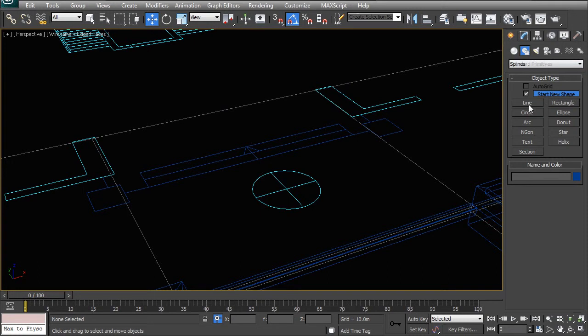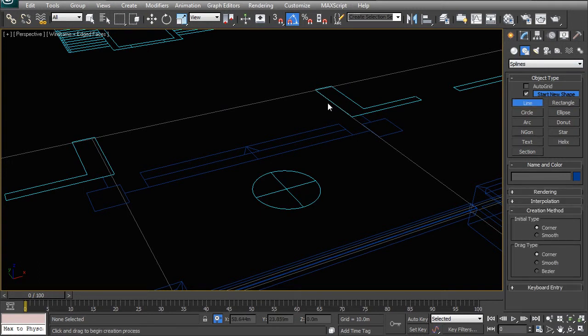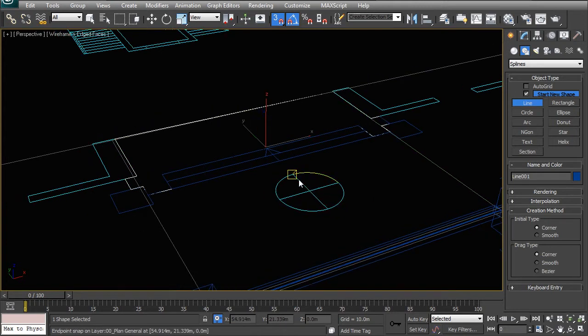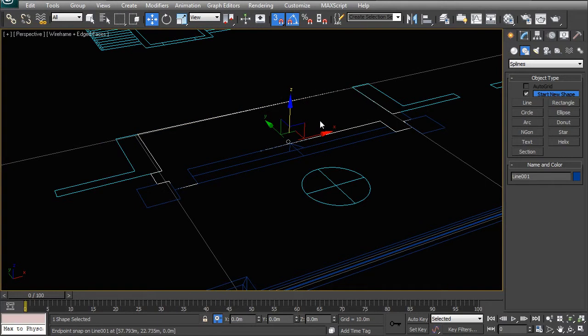So I'm going to start drawing that slab by doing a line, and selecting my snap, I just trace what the CAD information is giving me. And I'm going to select or at least trace the uppermost layer. I'm going to close that spline, and this will now be at zero. And all these steps will move down from it.